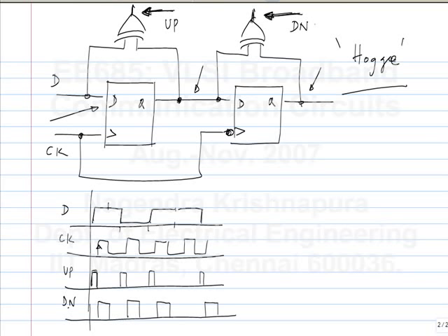That's true. It's not to say the density is reduced, but basically, this is known as consecutive identical digits. You have a large number of identical bits. So what happens is now the loop filter is not getting the correction anymore. The loop filter voltage on average equals the correct value required to get the right frequency. It does not mean that at every instant it is at the right value. And if you don't have any transitions at all for a long time, the VCO frequency is slightly different from the data frequency. So the transitions will keep on shifting. At some point it will just start sampling the wrong symbol.